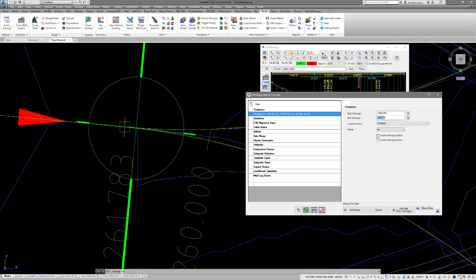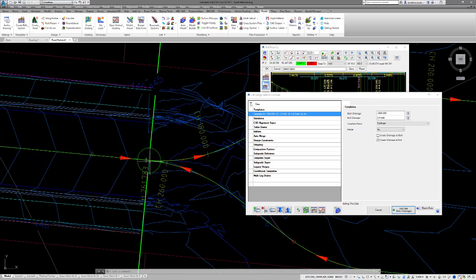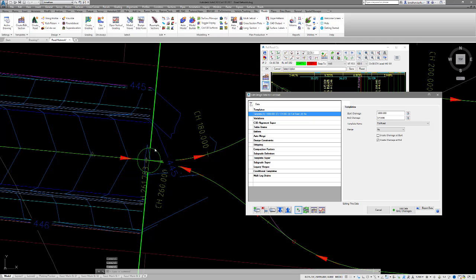You'll see that we've got a chainage there, which actually isn't a sample chainage. So to apply that chainage value, I need to click on the Create Chainage at End and make sure I pick Add Data Entry Chainages, which means that that chainage will be added to the samples list. Now I've done that, and immediately in the background you'll see that the template has been taken back to that chainage, and auto model can now just be tidied up by striking auto model.